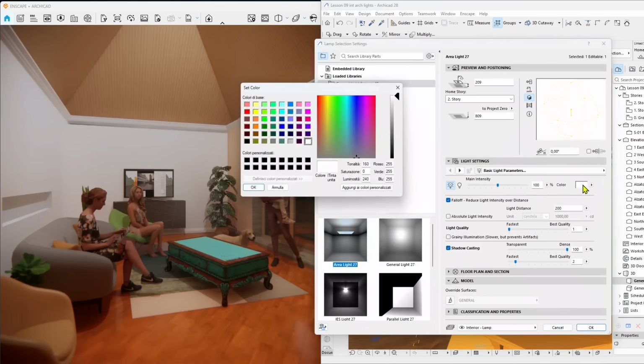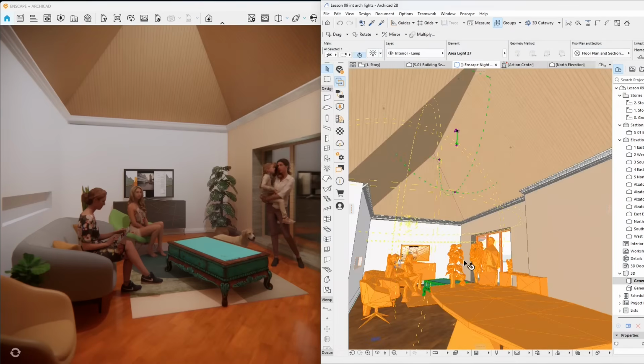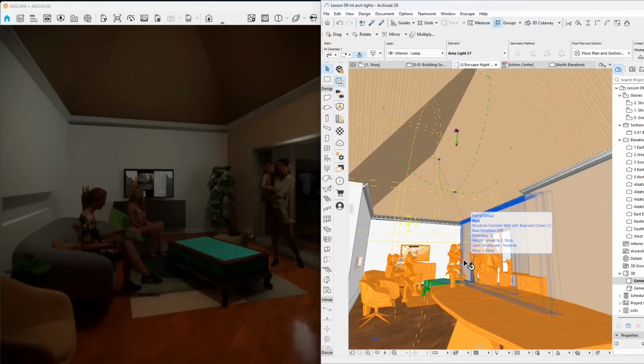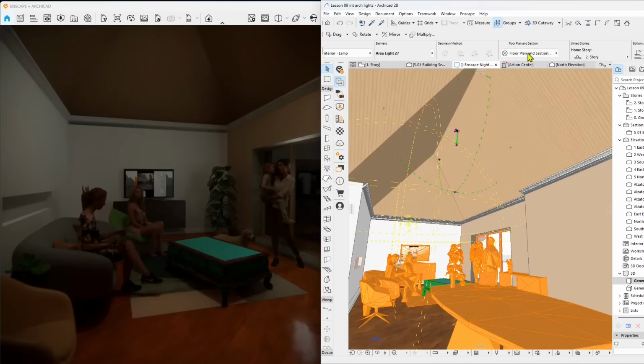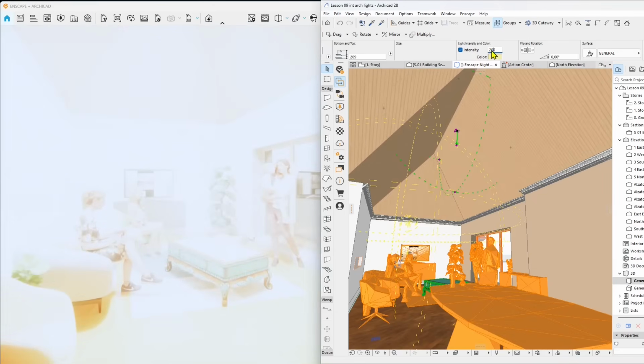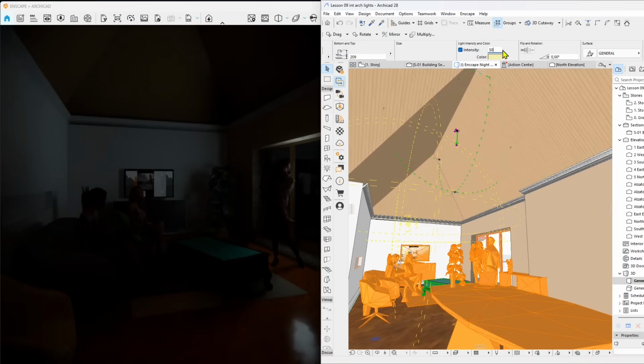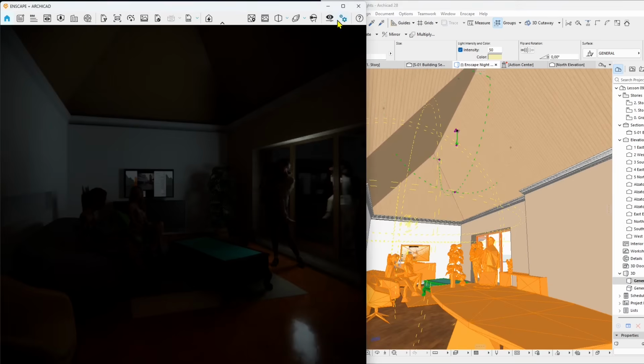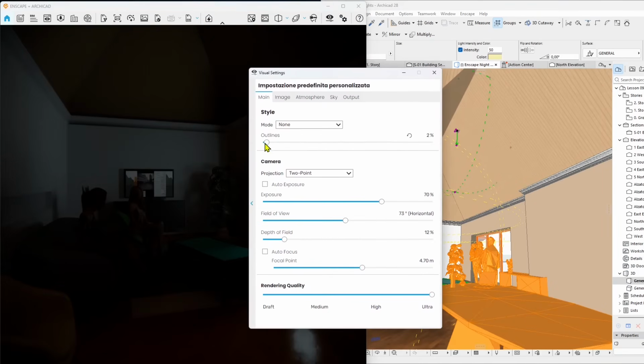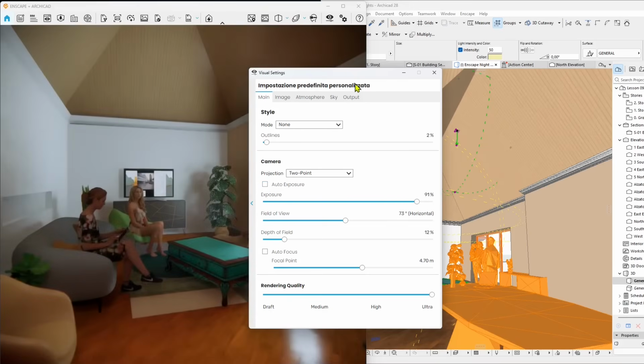And we can continue here just to modify, try to change the type of light, like from a general here into a planar light. But I can also do more. I can change intensity, the size. Now it's too strong. So I'm just gonna decrease it again. Now it's too low. So everything is a balance. And also you need to balance using not the general settings, but the visual settings. So the exposure of the camera, really important. So balance here